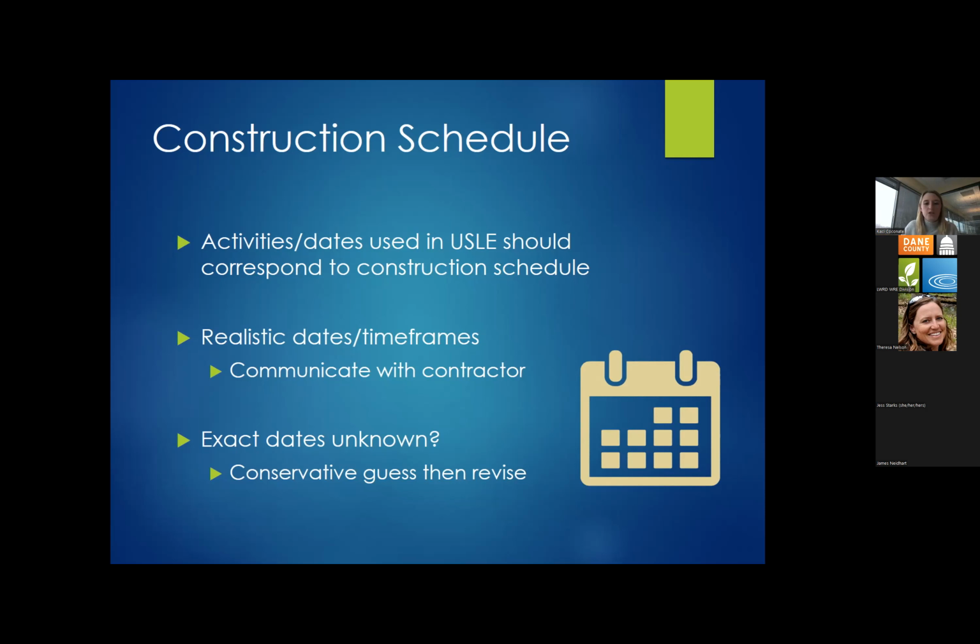If you have a shorter project and you're not sure when it's going to actually happen, but you know it's this summer and you want to apply for your permit now, one option is to model that slope during the most erosive time period. And if it meets the soil loss requirement during those first few weeks in July, we can assume that it would meet the soil loss requirement during any other time throughout the year.